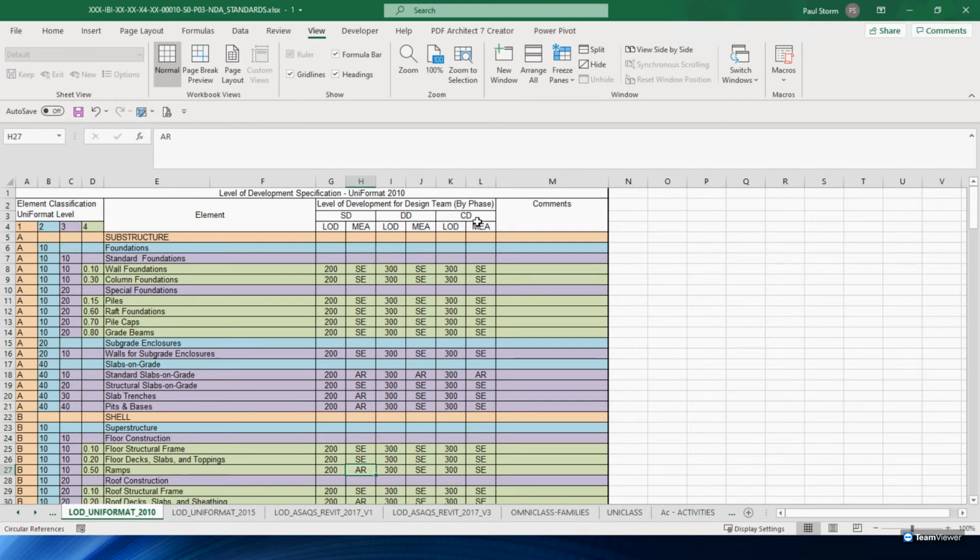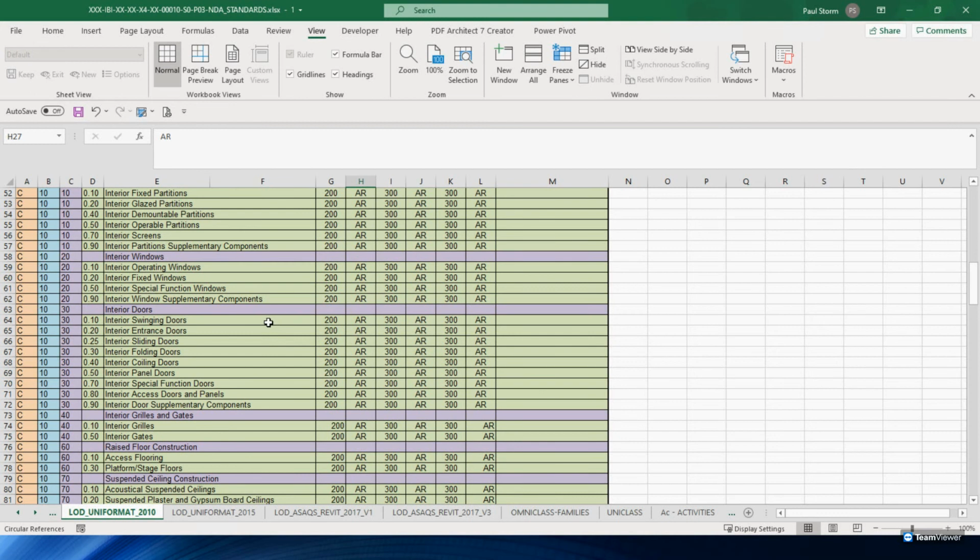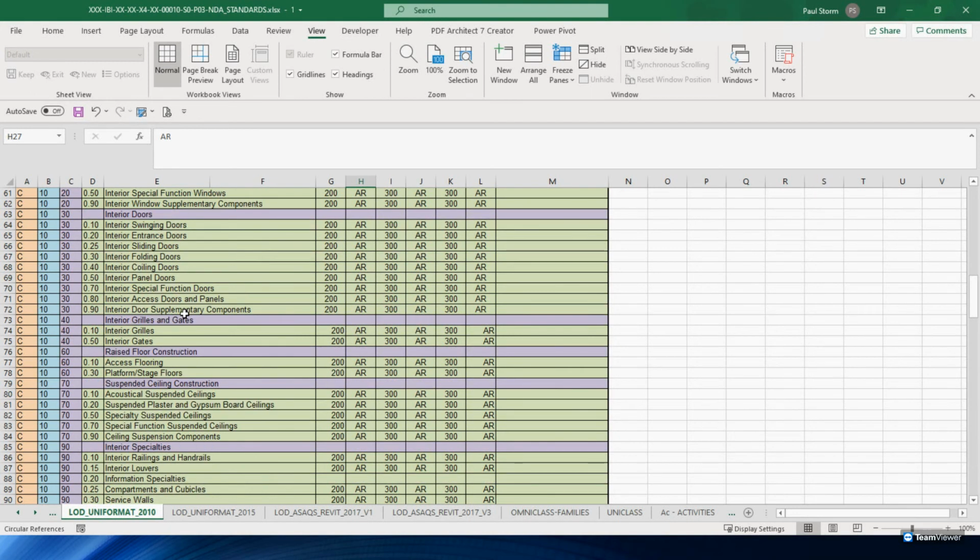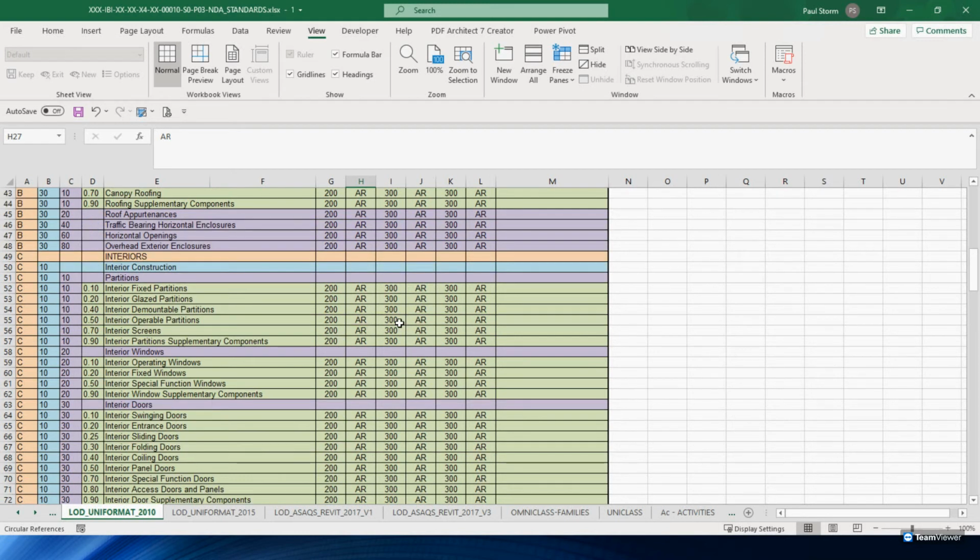Because if you had to do, say, a preliminary rendering of a room and you find that you've used a kind of placeholder family for chairs or interior walls or whatever, then you can switch the families out. You can park a model parallel to your model in time, and you say, I'm going to model this part of the building. You isolate that part of the building, and then you switch out the families into a more developed family just to get that visual representation back at you.